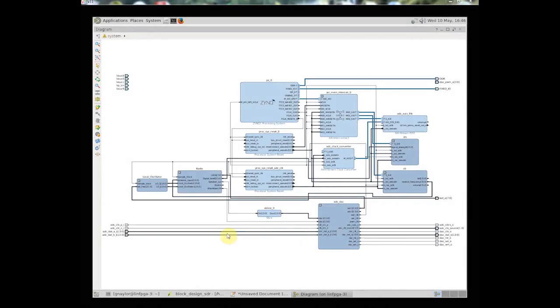Now there's one more thing we can add, is to stream some data out from this process. We're making use of the fact that we put a FIFO on this bit of logic, so we can read this out from the ARM. We set up the drivers to be able to do that, and that'll be useful from a graphical application to be able to pull out data and display it to see what's going on. Now if you remember, we had this clock converter which takes data from the ADC clock domain and puts it into the ARM clock domain ready to go into the FIFO mount.